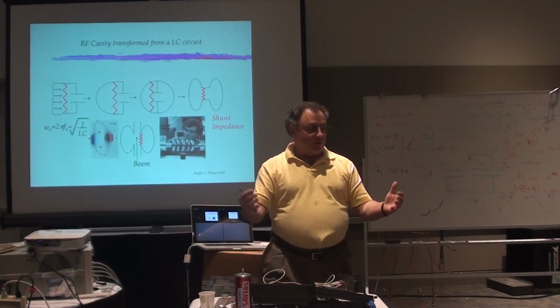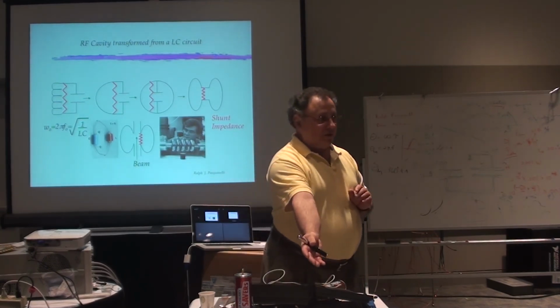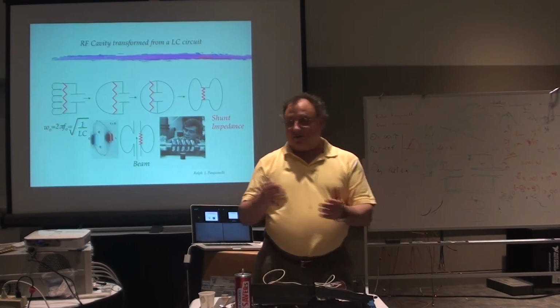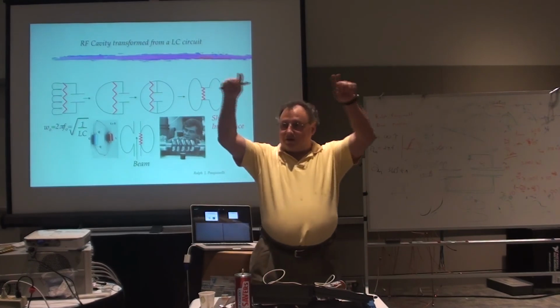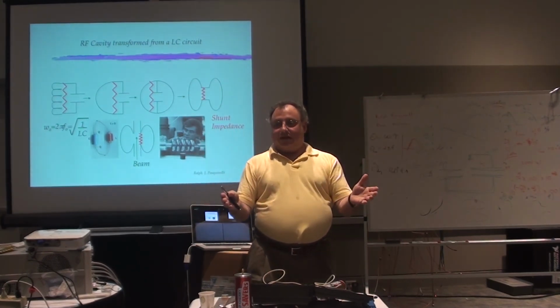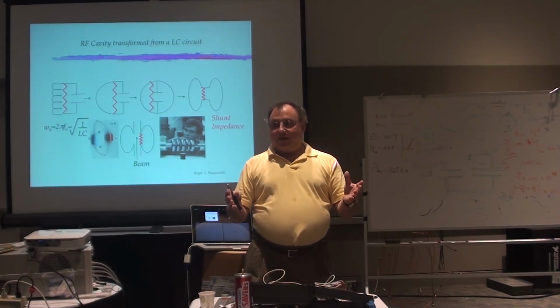So everything has to be perfectly balanced. And the way you make something perfectly balanced is you have to have some kind of a splitting device that has absolutely excellent amplitude balance and excellent phase balance, and then you cut all the coaxial cables to the exact same length so that when you deliver it to the cavity, you get the power delivered to each cavity equally.